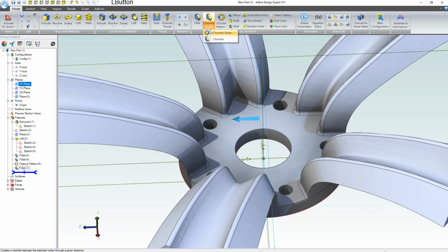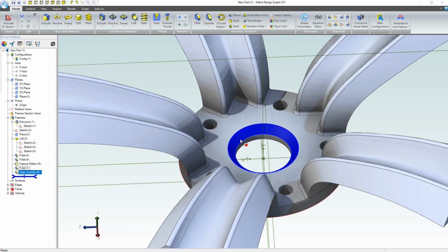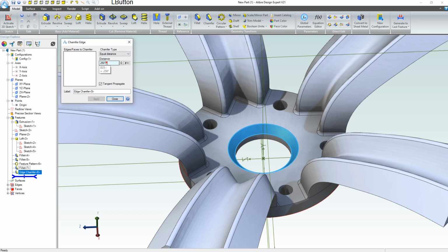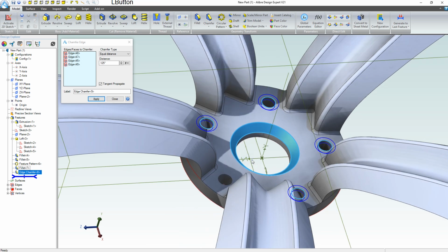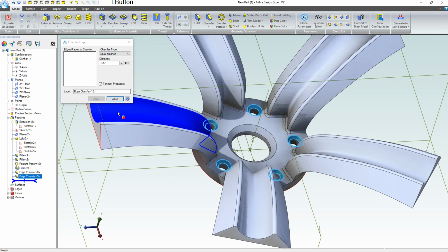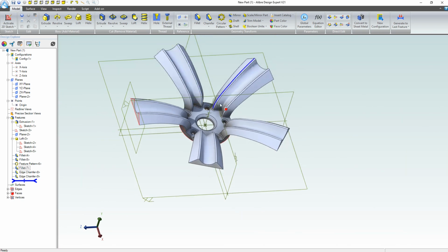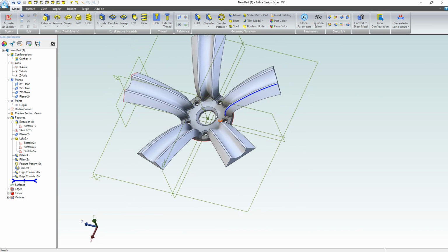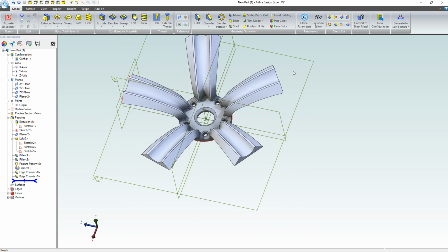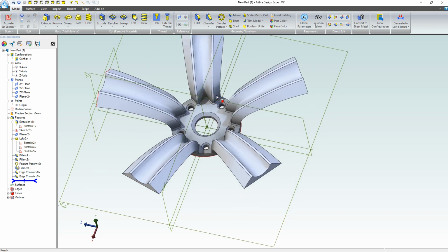On that same note, I want to check out this chamfer, right? Maybe I can add some chamfers. A 1/4 inch chamfer should take us halfway down that hole. So let's apply that. Works nice. And also, let's try a 0.125 chamfer here. Excellent. Superb. Again, fillets and chamfers should be at the end of a design. I'm just way too excited to start to see this wheel come to life. I made up those spokes right on the spot, and I'm quite pleased with how they're looking so far.